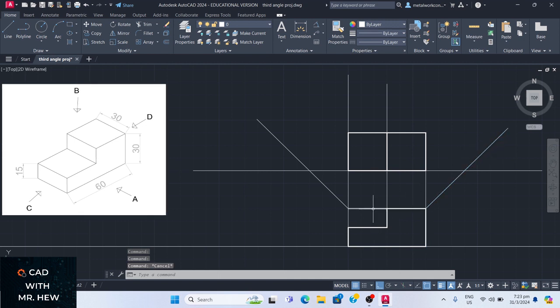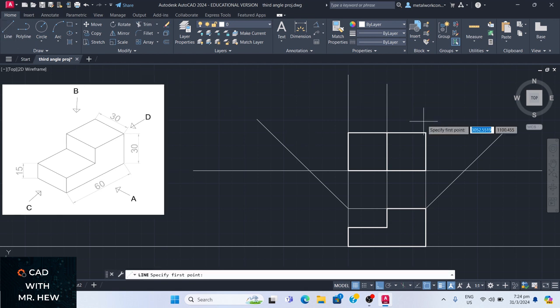Then the highest point on the front elevation will be where this construction line intersects this vertical line, and where they intersect, you draw this 45 here. Good? All right. The purpose of the 45, as I indicated not too long ago, is to transfer the width of the plan, the top view, to the end elevation, right? So to draw the end elevation now, what I need to do is draw a line from this point, the width, going across to intersect the 45-degree line.